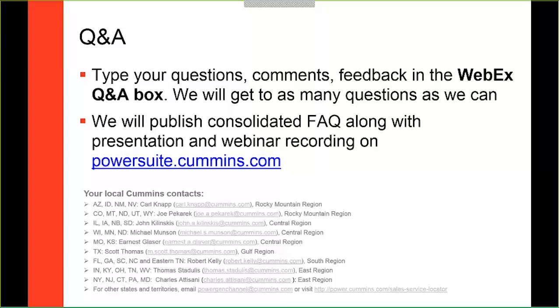Okay. Next question, Mike. In ISO 8528, ESP or PRP has a 70% average load factor. Does this percentage vary by manufacturer or model? Great question. To reiterate, ISO's expectation is that the lowest number that a manufacturer can adopt is 70%. So manufacturers can, in some cases, adopt higher average load factor ratings.